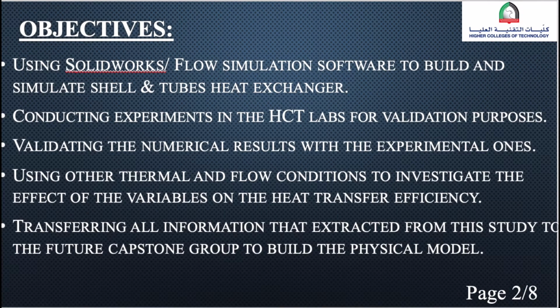The objective and final goal of our capstone project is to build a SolidWorks shell and tube heat exchanger model that resembles the physical prototype in the HCT ADM campus, run a physical experiment and collect the data results from the physical model, and use the flow simulation in SolidWorks to convert the SolidWorks model to a computational domain, using the same boundary conditions that were used in the physical experiment.